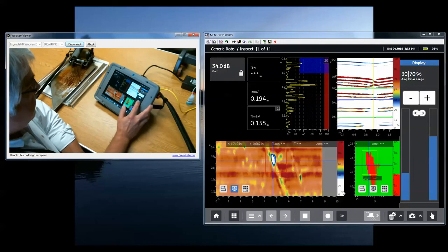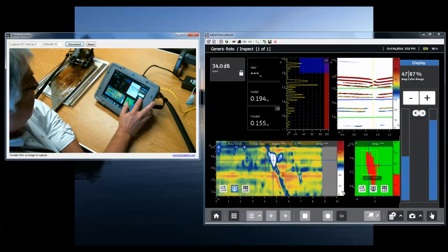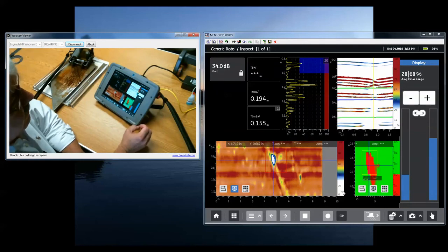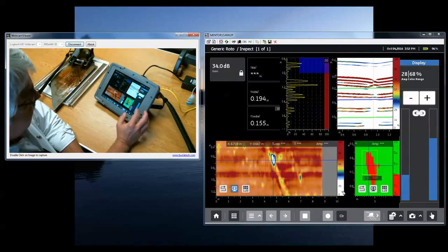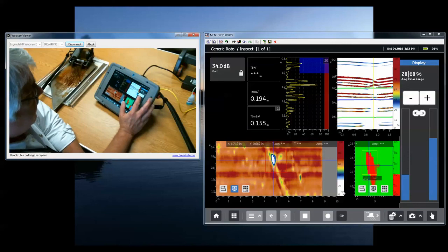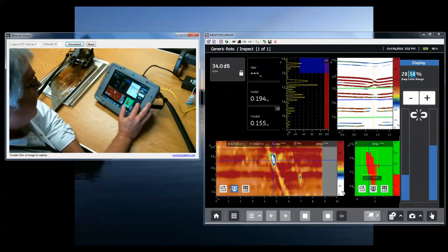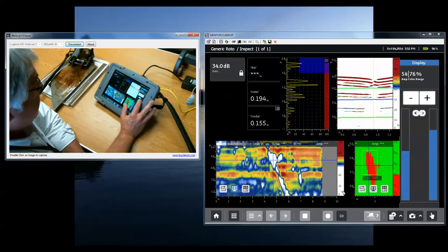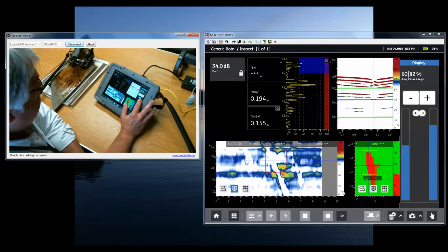I can link these two sides together, shift the entire palette up and down together. So this has the effect of creating sort of a contrast control. If most of your variation is happening between say 70 and 80% screen height and you want to really zoom in on that, compress your palette tightly, then move the entire thing up so that it resides from 70 to 80%.